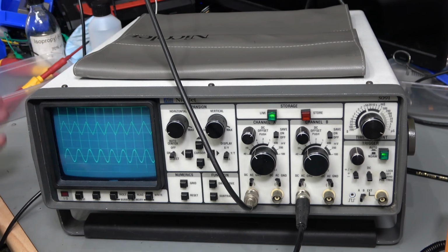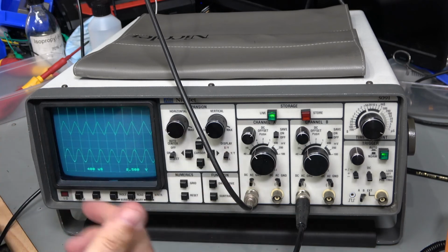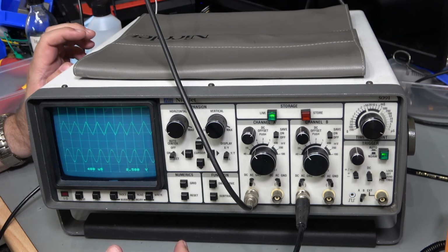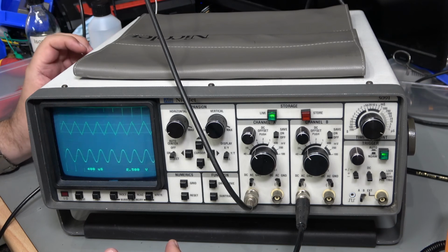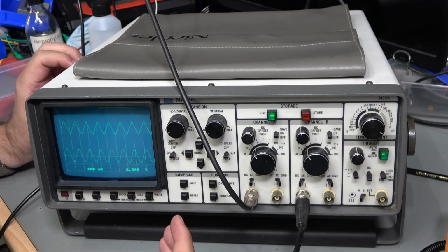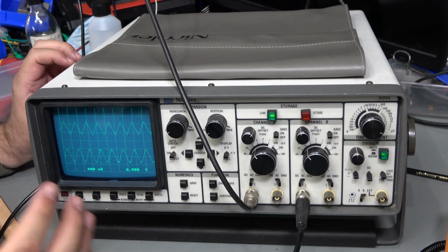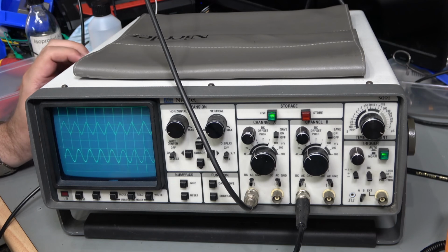I didn't really know that as I set off. I've got no circuit diagrams, I haven't even got an instruction book. I've got a specification sheet, and so that was a little bit challenging to fault find, and I did have a little bit of a cock up on there, and I ended up putting a new power supply board in, which I also wasn't quite sure was working until I understood that the voltage output on the plus minus volt is dependent upon the amount of current you're drawing out the 5 volts. So once I started drawing about 600-700 milliamps out the 5 volts, the other voltages came up, they behaved themselves,